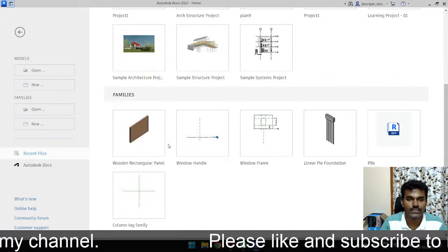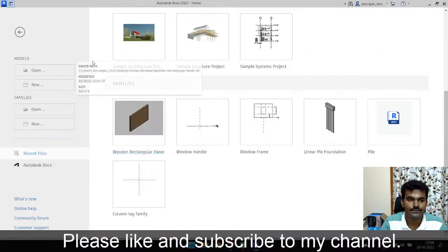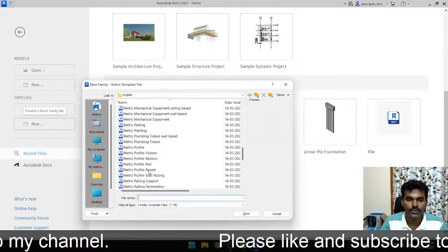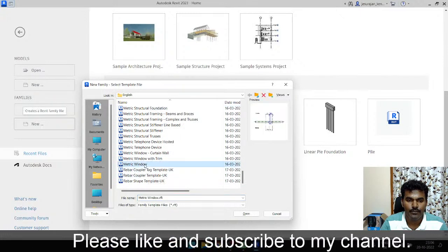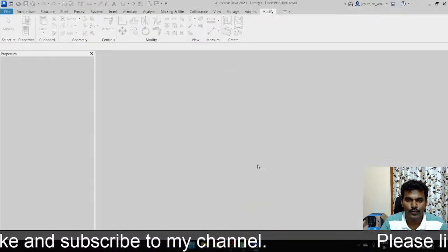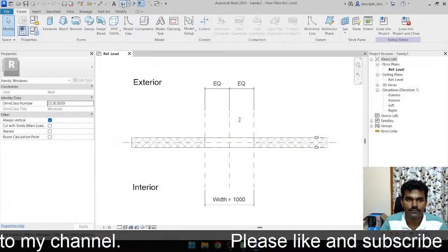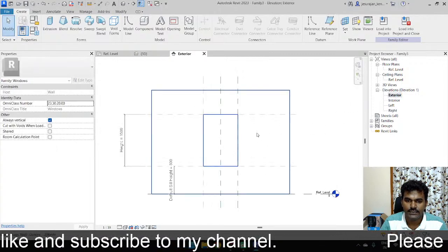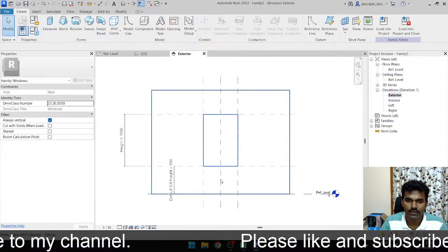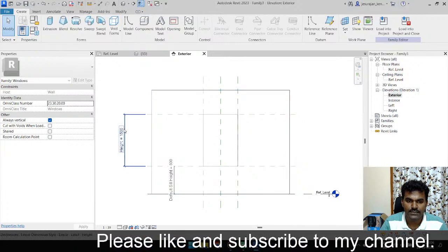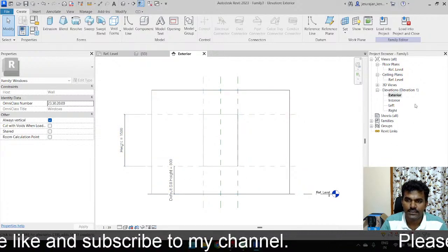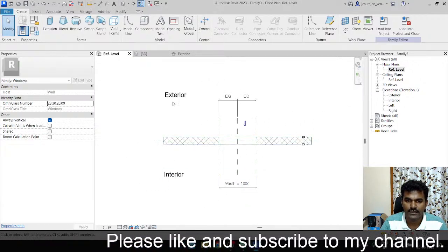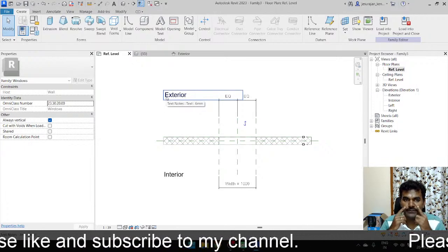Now let's go for Revit family. Go to family and create a new one. Now you can select metric window, open. So this is our main family. You can see the opening is already available in the metric window, and the sill height parameter and the width parameter are also available. You don't have to create anything, you just have to make your frame.